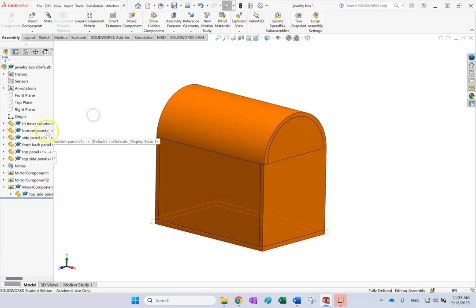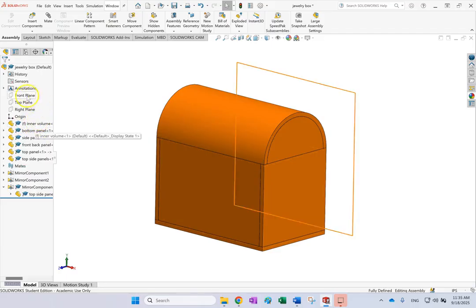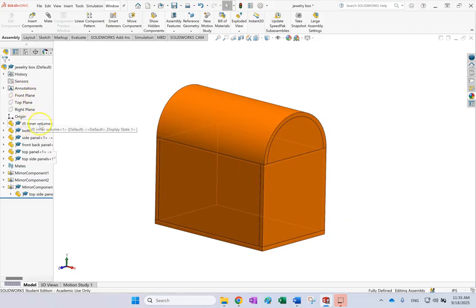Because if not, then these files that you made inside the assembly do not have access to the parameters of the text file that you imported into your assembly. So these individual components don't have access to assembly equations and parameters. So the way to go about it is to create what we call a template. And this is what I'm going to show you from scratch here.